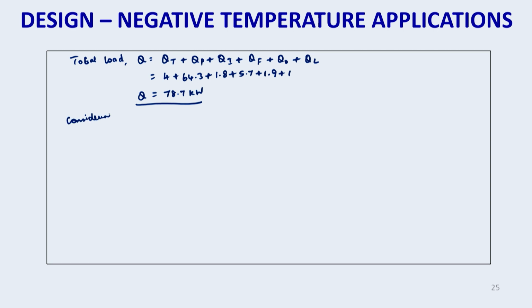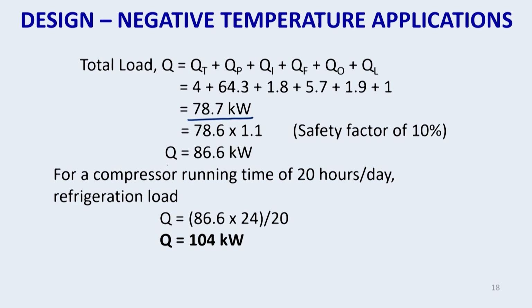Considering a safety factor of 10%, therefore total load Q is equal to 78.7 into 1.1, that is 110 by 100. So that comes to 86.6 kilowatt.